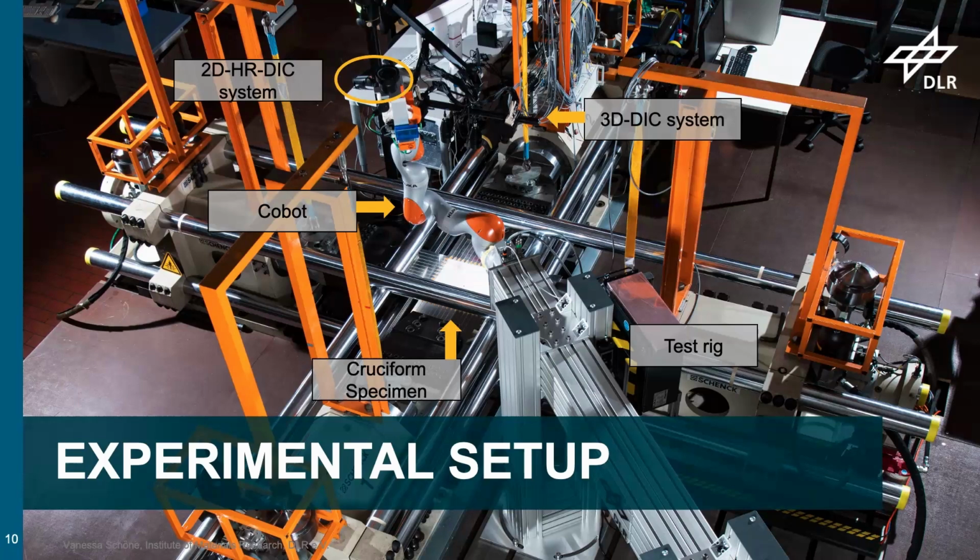We've got the test rig with 2 servo-hydraulic cylinders on each side. We've got the cruciform specimen in the middle, and we use 2 DIC systems. The first DIC system is over here. It's a full field, 3-dimensional DIC system that's capturing the specimen full field. The other system that we use is a 2D high resolution DIC system, which is actually a camera with a microscope on it. The system is being guided by a cobot.